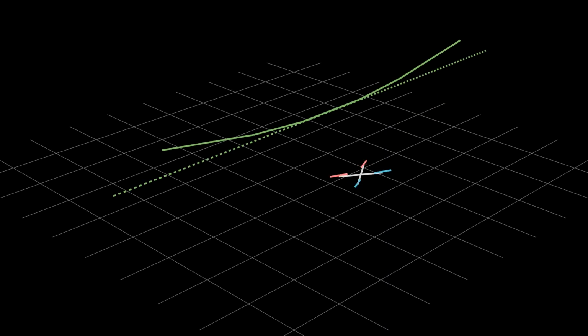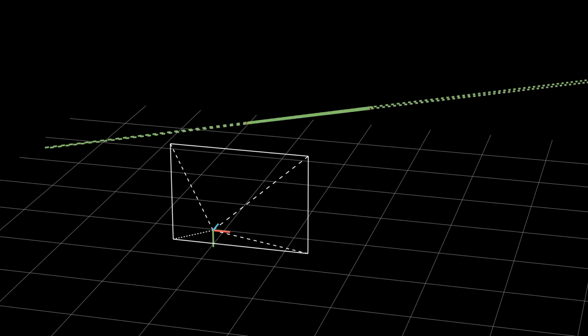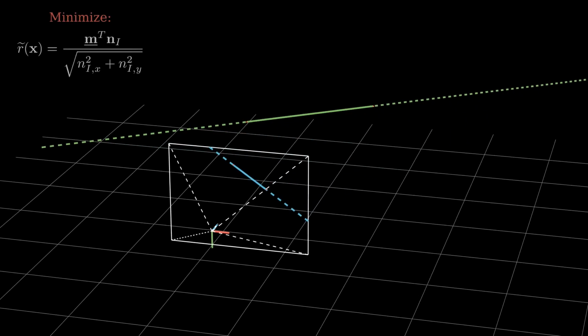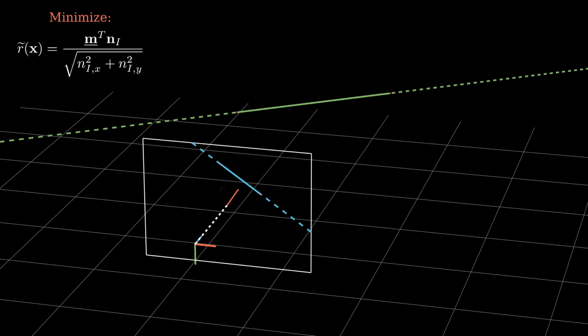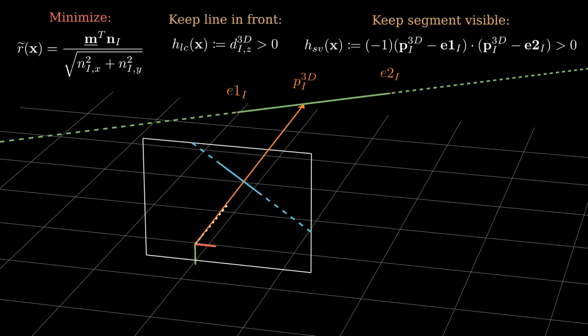In addition to collision avoidance, we are interested in keeping the objective power line segment in sight during the perching maneuver. This is useful whenever the robot needs visual feedback of the line to perform control or state estimation. To do so, we formulate the objective line in the robot's camera coordinates and minimize its distance to the center of the image. Additionally, we formulate two constraints to ensure that the segment is centered in front of the installed camera and that the segment is contained within the image.